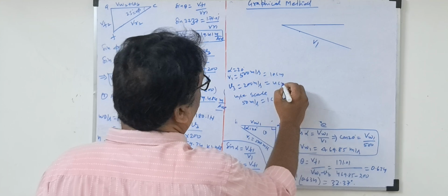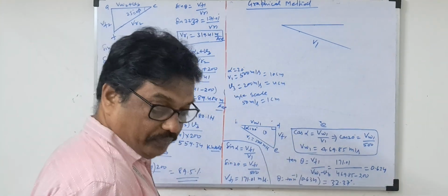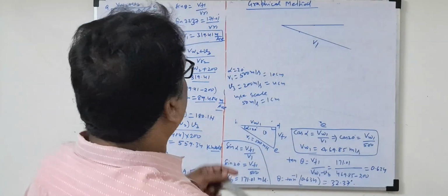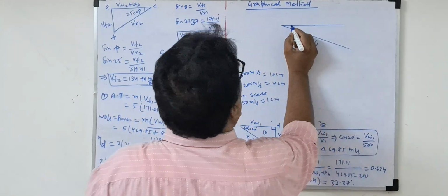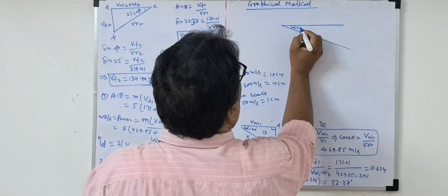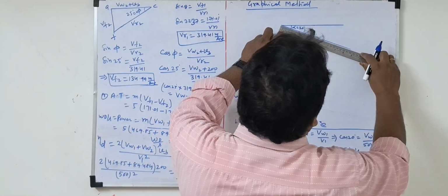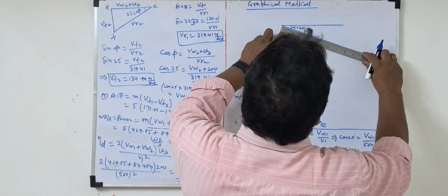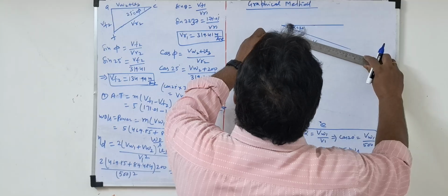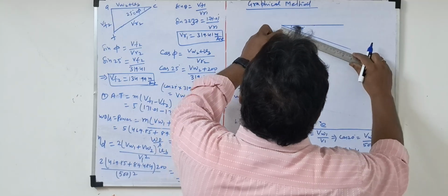This divides into 4 centimeter. So what we'll do here? We'll cut from there 10 centimeter, because this alpha we draw 20 degree. Alpha we draw the 20 degree. Now from there we'll cut the 10 centimeter. So we draw the, then we'll draw the 10 centimeter.